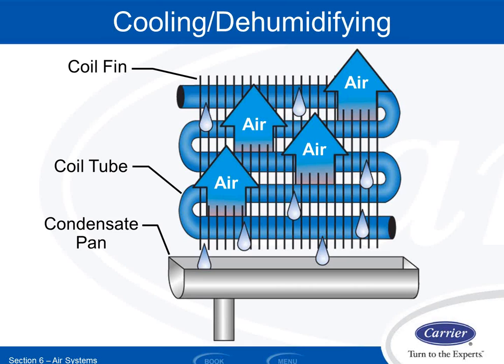So I've got a lot of moisture available to me, and I have this cool surface area, whether it's the windshield of my car or the grass or whatever. I can condense on that surface area. So the same thing needs to happen here. I need to drop the temperature of the refrigerant, and hence the air, down below the dew point of the air. And once I'm below the dew point, then I will start bringing moisture out.